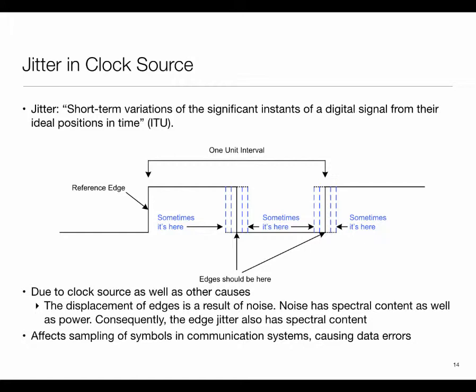And the problem that happens is that in some of these radios, in this particular case a radio from TI, internally they have a state machine. And which state the state machine happens to be in when you begin to communicate with it matters. If it's in one state versus a different state, then the first bit that goes out may see a different amount of delay. So there's a whole bunch of internal things that may come in the way, and an otherwise accurate source, just the way you talk to it, may cause additional problems.